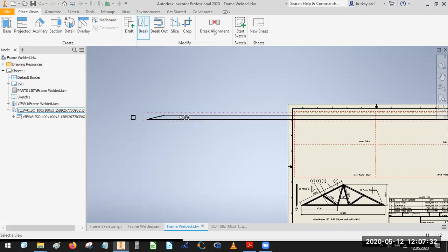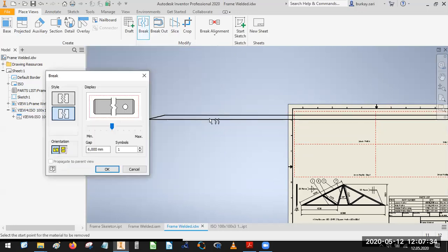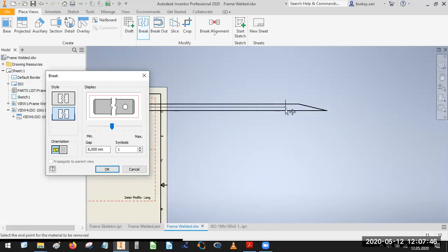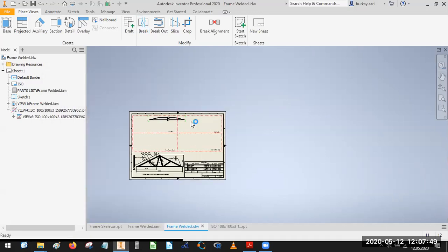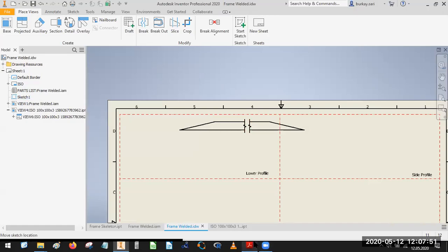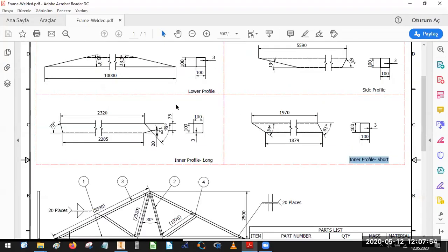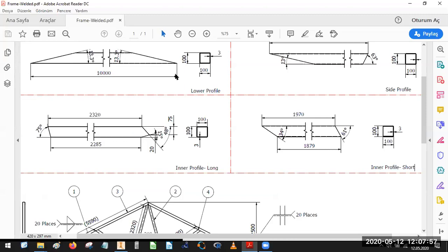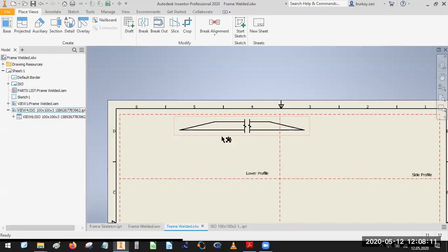this view, as you see. The software waits for the input points. I will just delete this point and this point so far, because the endpoint details are important, because we need to define this angle and the length information. Length information is for material supply purposes, and the angle information is for manufacturing purposes. I need 2 dimensions for this profile.